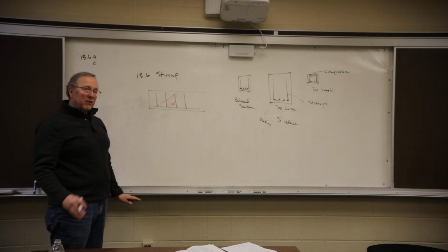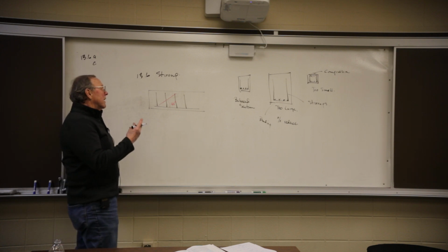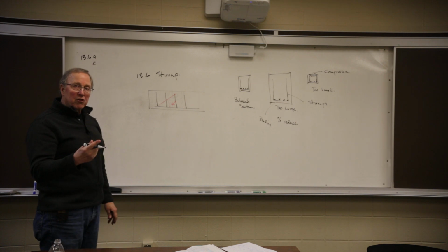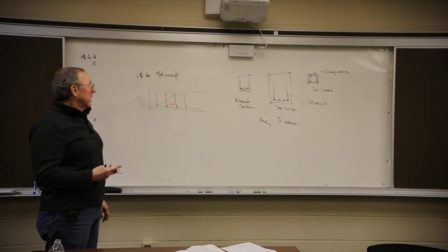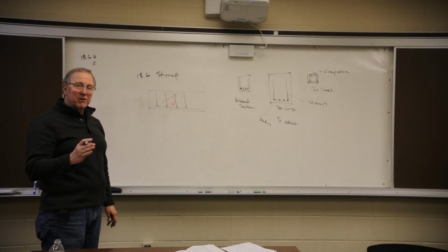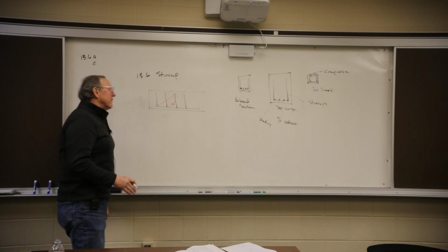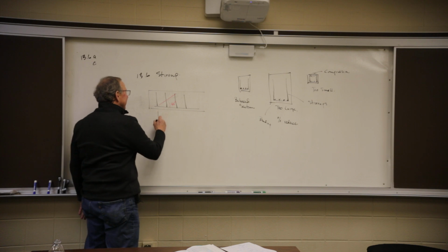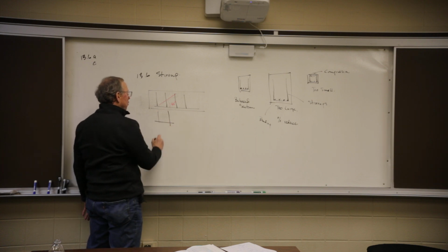So the stirrups have two purposes. One is to take the shear out. Two is to facilitate the installation of longitudinal bars. Okay, now we have two possibilities with those stirrups. One is that they're spaced at code minimum.